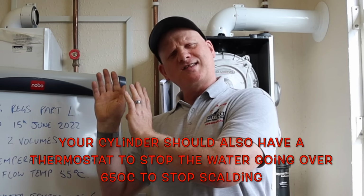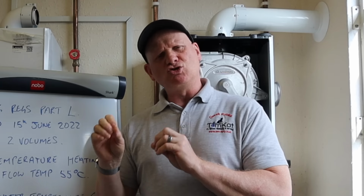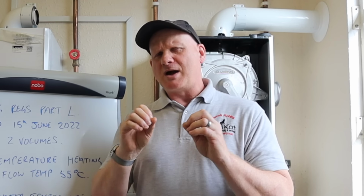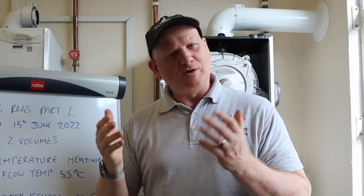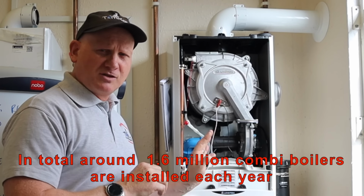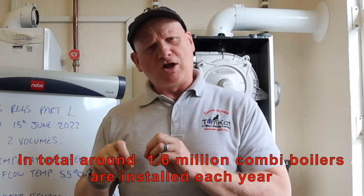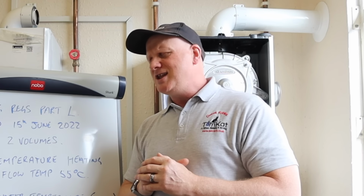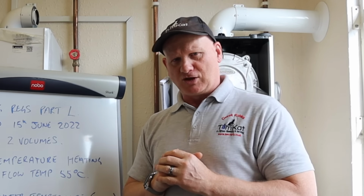So if you've got your boiler set at 80 degrees and you've got a cylinder, then you can adjust your flow temperature to about 60 degrees on the boiler and see how you cope with actually running out of water or not when you need it. But if you have one of the most common boilers in the UK, the most common boiler sold in the UK is the Combi Boiler, you can adjust the flow temperatures for the hot water and the heating separately. But there's some things you need to think about before you actually start going and adjusting that flow temperature.